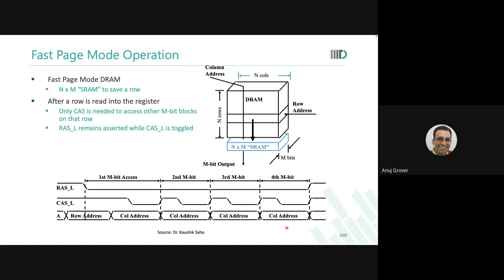It is for one set of words, one line you may say. So one thing is clear, that I have read 256 words or 512 words in one book, and now depending on my line length, I want to read 16, 32, 256, all of them out. And I do not want to go into the main DRAM again every time I want to read the next word. All this data that I read once has to be stored somewhere.